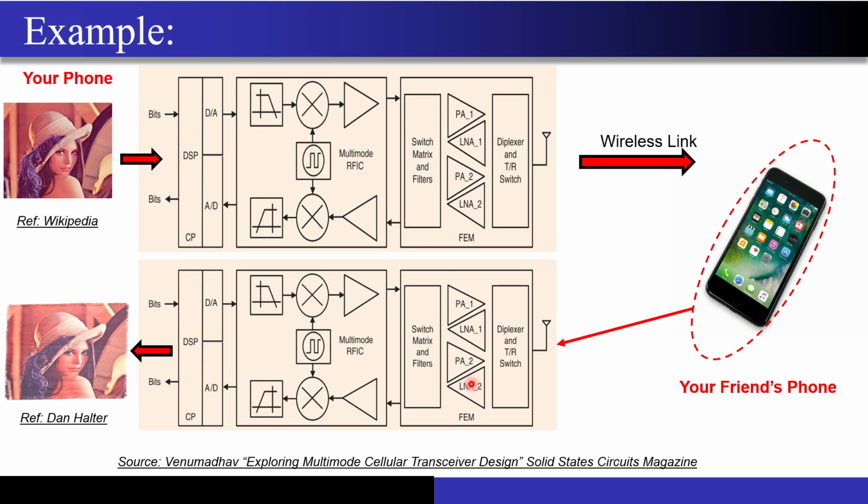For example, if you have 15 dB of SNR at the input of the amplifier, then at the output you may be losing around 0.5 or even 1 dB of SNR. Correct? So each and every amplifier will add its own noise and degrade the SNR. Now how can I design an amplifier which will add as little noise as possible and also amplify at the same time? That job is done by this low noise amplifier.